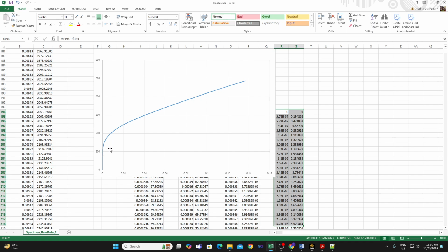Okay, so in the initial part the slope is gradually dying down and ultimately becoming zero, but then for one particular Chaboche term, so we are guessing there are more than one Chaboche term, and it is a good guess to take between 2 to 3 Chaboche terms, and to be on the safer side we are taking 3 Chaboche terms here. And let's say for the third Chaboche term, the slope is constant, and basically it's a linear term, and for that linear term it seems to be having a slope of 2 GPa or 2000 megapascal. So we have a rough estimation of that.